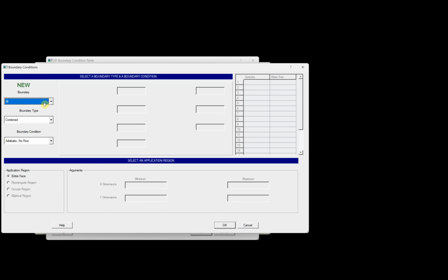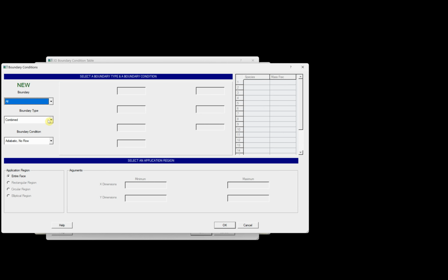The next thing we want to do is add a wind boundary condition to all faces. And that is a momentum condition, wind, x component 0, y component will be negative 3. It's flowing from y max to y min, z component 0. Next, we want to add hydrostatic so that it can flow out everywhere. I believe that is also combined. Yes, here it is, hydrostatic, and we give it a temperature of 350.